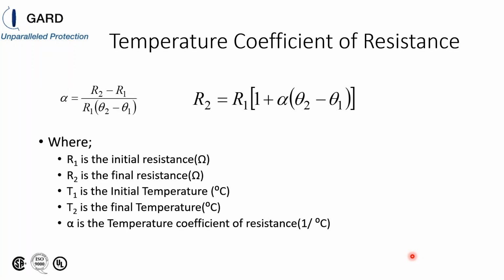Sorry. So the temperature coefficient of resistance, and I know we've seen these terms in CSA, or sorry, IEEE C57.32. So alpha is a temperature coefficient of resistance, and it's expressed in 1 over degree C. What it basically tells you is there's a somewhat linear proportion of a resistance change per degree change.